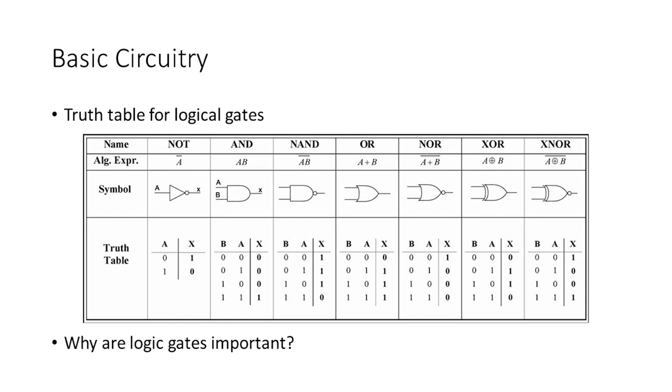The exclusive OR only wants a single input to be 1. If both inputs are 0 or both inputs are 1, then the output is 0. Otherwise, when one of the inputs is 1 and the other is in an opposite state, the output is 1. The exclusive NOT OR requires both inputs to be the same value, either 0, 0 or 1, 1, in order for the output to be 1.